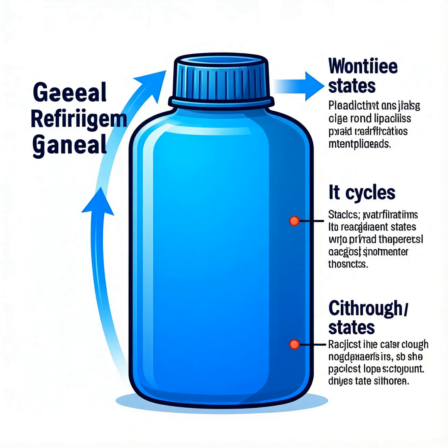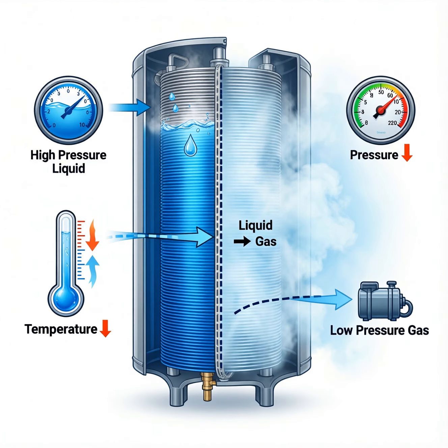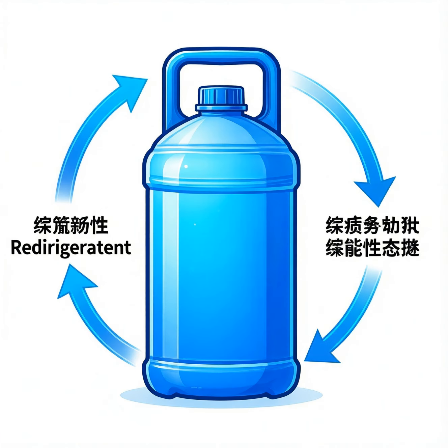We meet the refrigerant, a fluid that moves through the system. It starts as a low-pressure liquid inside the evaporator coil. When it absorbs heat from your room, it turns into vapor. This phase change is called evaporation and absorbs latent heat. The vapor then travels to the compressor where pressure rises dramatically. Higher pressure pushes the temperature up, making the gas hot.